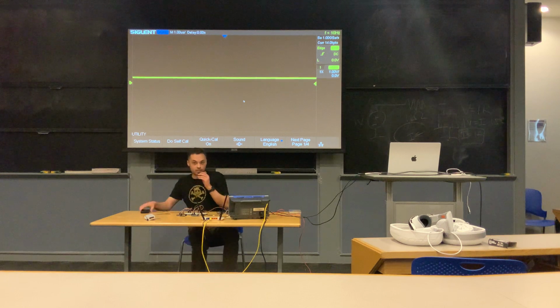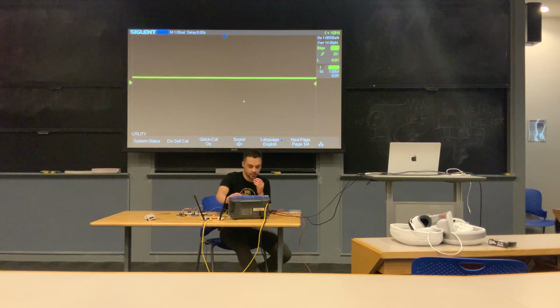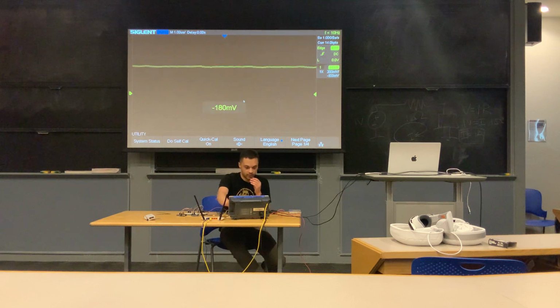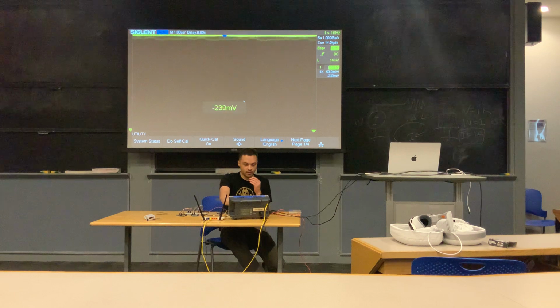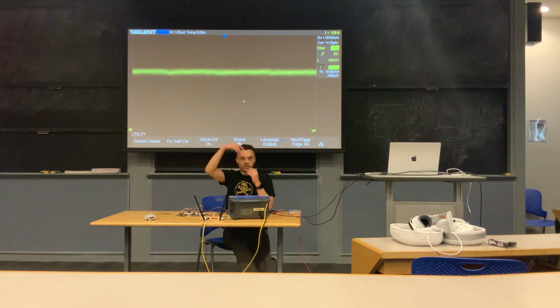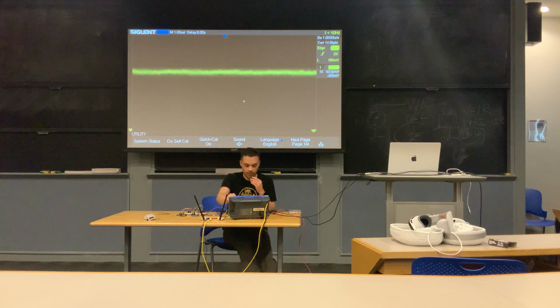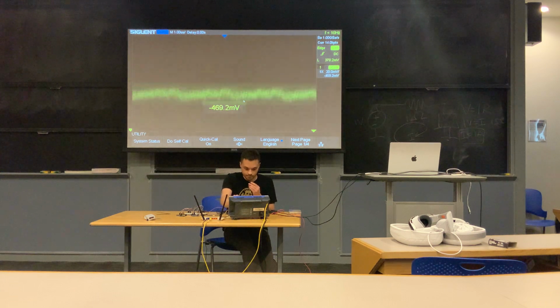Now we are attached to the power line. You can see there's very little fluctuation because it's a very tiny difference here. So we're going to zoom in and see if we can capture something. What the chip is doing is every 100 milliseconds, it's going to compute RSA and then shut itself down. So there'll be some noise, or some signal, and then it'll stop itself. We should be able to see the signal pretty clearly.